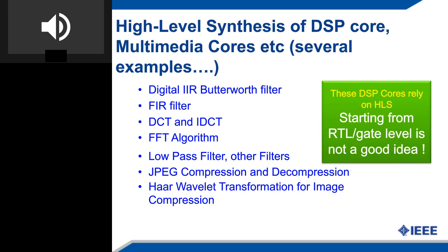IP cores are susceptible to hardware threats of IP counterfeiting and IP cloning. There's a small technical difference between the words counterfeiting and cloning, which I'll talk about in the upcoming slides. But it's important that hardware needs to be secured against counterfeited and cloned versions. These threats have emerged due to the globalization of the design supply chain. Importantly, this is such a critical threat that needs to be addressed because it can sabotage the reputation of a genuine IP vendor and can also cause huge revenue losses. So both digital signature and IP core steganography can help in providing forensic detective control against such threats of IP counterfeiting and IP cloning, by implanting a robust, invisible, secret mark as digital evidence into your DSP cores or your hardware accelerators, which could be a reusable IP core as well.